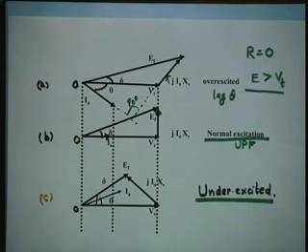You must have done in your undergraduate practicals the V curves of the synchronous machine. So, you can operate the machine from lagging to unity power factor to leading, which is not possible in an induction machine or any other machine. So, that is why it is a versatile machine, and it can supply negative watts, positive watts, or anything.